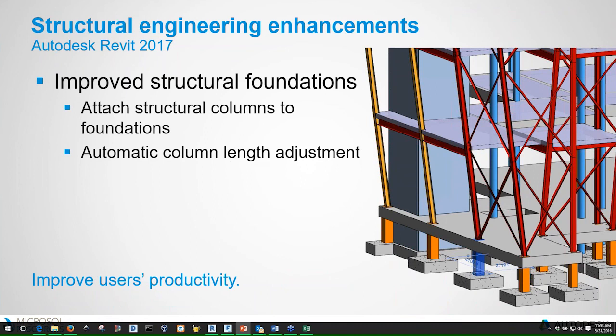Last but not the least, you can now attach structural columns to isolated footings and foundations. The byproduct of that is that if the footing were to go lower or change in size, the column would still remain attached to it. And this just makes life easier for people working with these systems. They don't have to manually go and join things or update things.